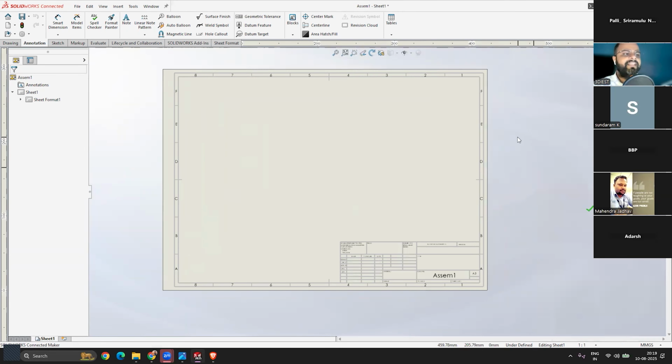So the first thing we did, we selected a pre-prepared drawing format provided by SolidWorks, and there I selected the right paper size that is needed. And that is, let's say we have a printer that can print A3 papers, then we'll use this paper format.